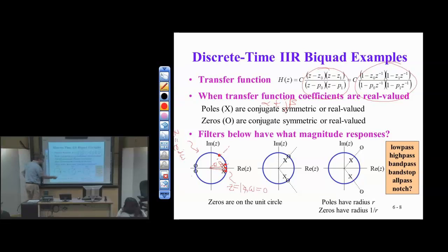Now, if I look at higher frequencies, go all the way to pi and minus pi, I'm now close to the zeros. So I look at frequency pi or minus pi, trying to get on the unit circle there. So at z equals minus 1, this is the highest frequency possible. This is omega equals pi. It's also omega equals minus pi, and 3 pi, and minus 3 pi, and so forth. All right. So this is the highest frequency possible in discrete time.